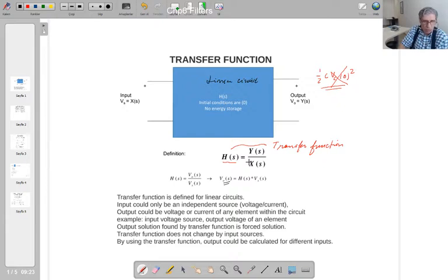So in a linear circuit it is true, isn't it? We were saying in a linear circuit the output voltage or current, when you found the solution, your solution is going to be like that. So that means you're going to write the output element voltage in terms of the source function, isn't it? Source function determines all the outputs, critical. So if you try to find out the transfer function, you're going to remove that Vs. So in here, Vs is not included. That is the transfer function.